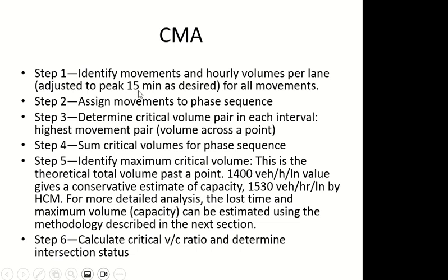Okay, this means convert the volumes to flow rates. Then you assign the movement to each phase sequence. Then you determine the critical volume pair. What is the critical volume pair? The conflicting movements which will happen one after the other.